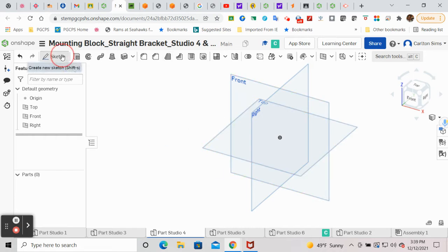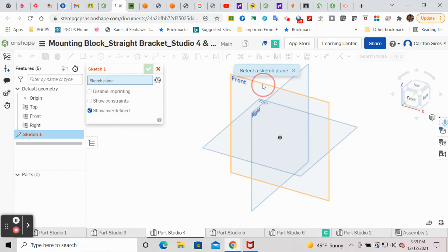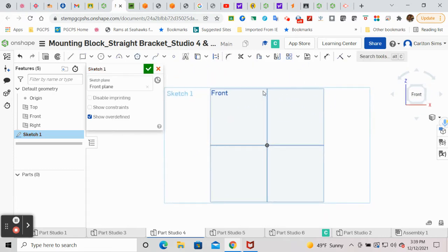So I'm going to hit sketch. I'm going to start this on the front plane. I'm going to hit N to normal fit. And I'm still going to continue my unusual process of creating two construction lines, just as reference lines, if necessary. May not be necessary to use them at all, but sometimes it is necessary to use these as a reference point, or connect to them as a reference point, and it oftentimes can help you with clearly defining your sketch. Okay, so we're going to start this off with just the line tool, which I'll leave activated.